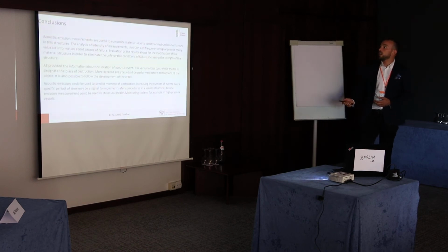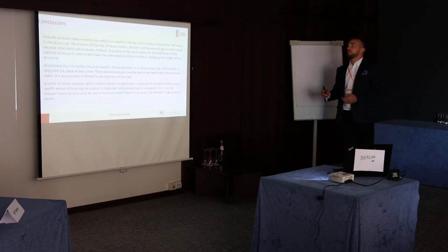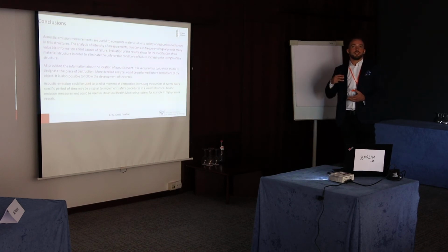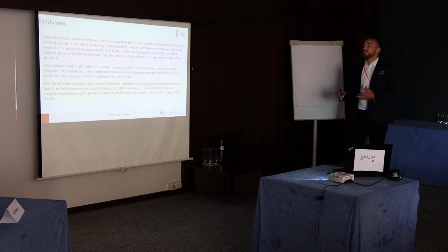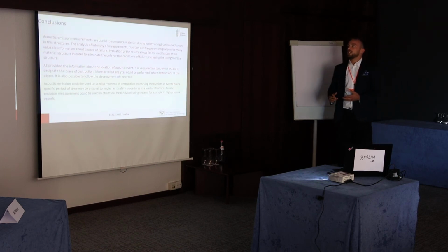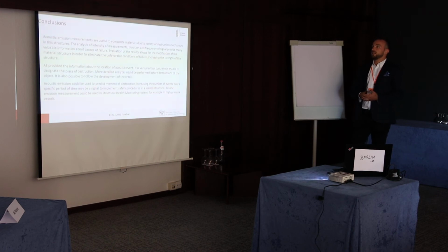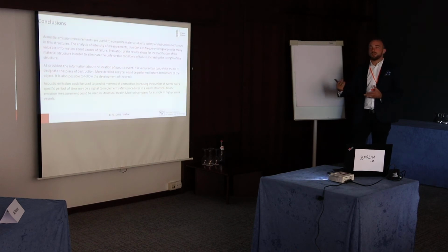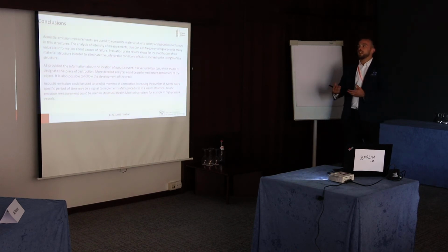Okay. And conclusions of our research: we can use the acoustic emission system to check the destruction mechanism in our composite material, to obtain the frequency, the amplitude, or the duration of the events due to the failure in our composite. So after the evaluation of the results, we can say that we must change the resin used for impregnation of our fibers.